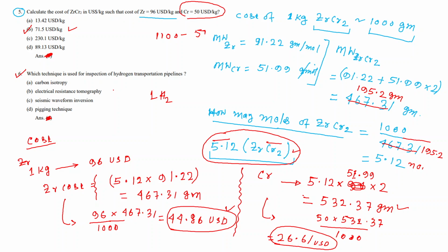Hydrogen gas may diffuse, and if the material is not up to the mark, there may be formation of hydrogen embrittlement of the metal, maybe some corrosion of the gas pipeline. So inspection is very important, and maintenance cost is very high for carrying hydrogen through the pipeline.